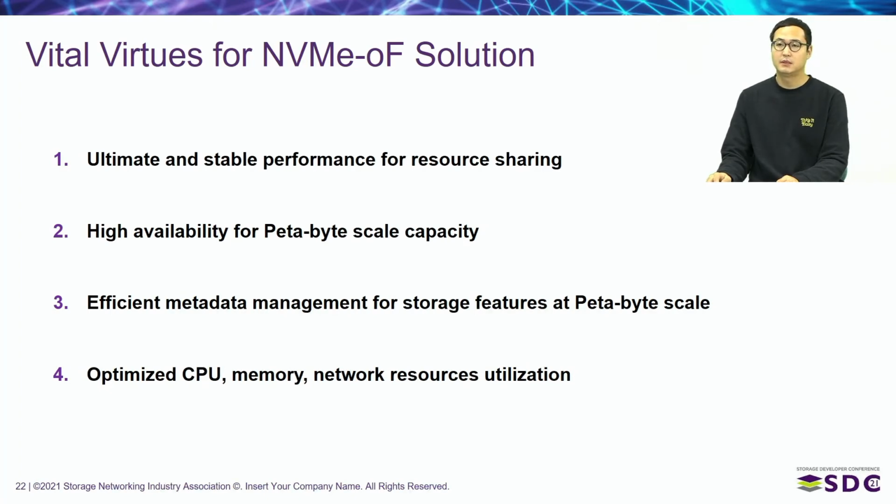Second one is, it should be highly available. High availability is essential for storage systems, but this becomes more important in EDSFF systems. With high-density EDSFF SSDs, we can easily achieve petabyte scale capacity in a single server. So we need more considerations about high availability for NVMe Fabric systems, especially for EDSFF SSDs.